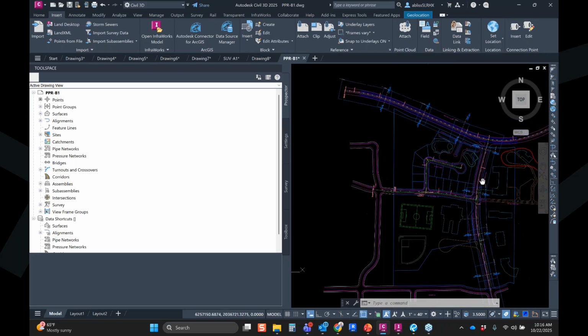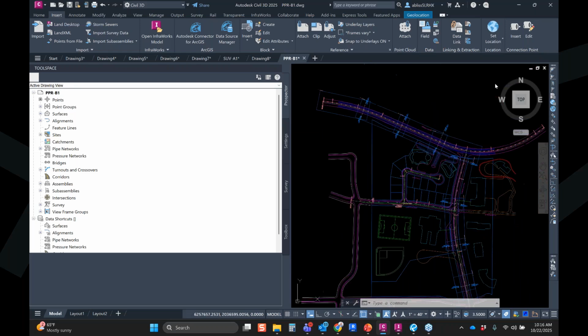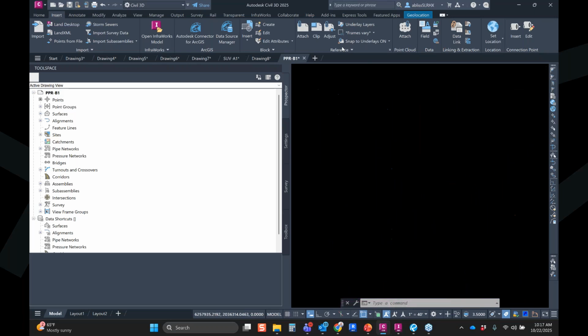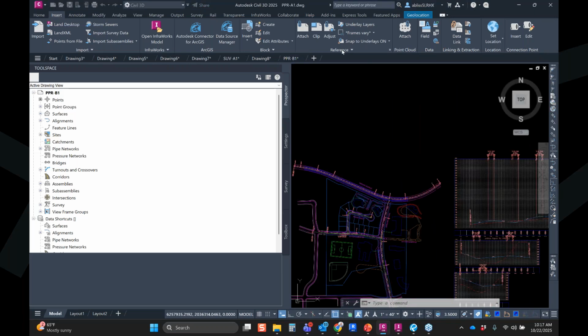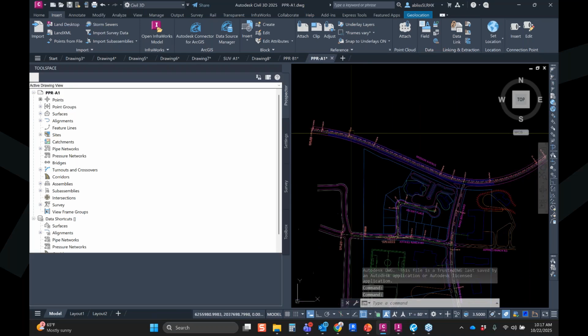So I already got some thrown on here. In this one, the view frames. Let me go back a work step. And we will throw some of those frames on as well. Just that process of setting a viewport in a drawing for the plan and the profile, panning, rotating that viewport, changing the UCS, panning over, zooming, getting it all set up for both the plan and the profile and the sheet.